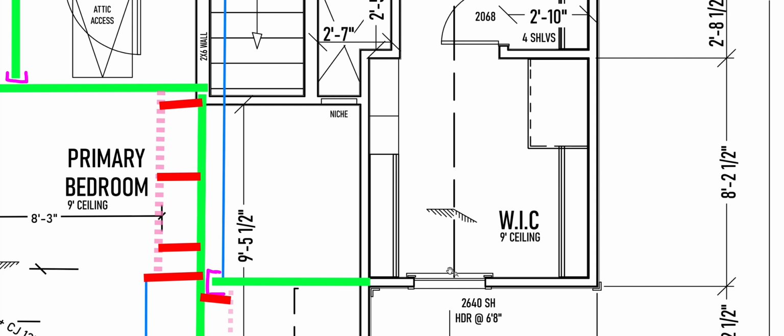This line right here is saying the ceiling is exactly in line with where the ceiling's at on this wall. So if my pitch was a 12-12 and it was exactly 45 degrees, then I would know exactly halfway between here and here is where that spot is, where I could come up at a 45-degree angle into my roof. But the roof's not at a 45, it's just close.